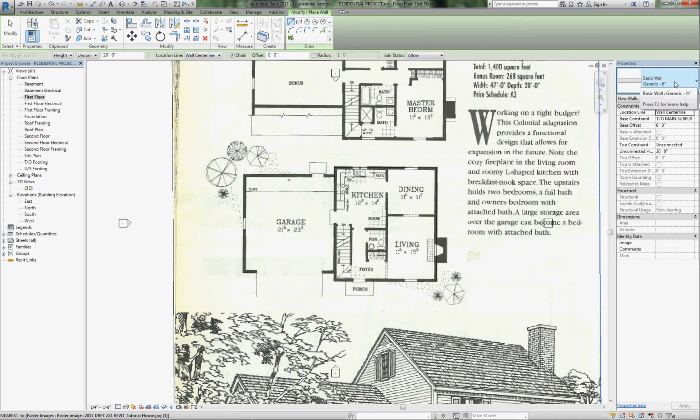Now that we've got the floor plan image inserted and the rotation correct, we're just about ready to trace over our walls. If you look closely, you can see the exterior elevation icons here, and our image is not quite centered on that. So I'm going to take my image and the few lines that I've drawn, careful not to include the exterior elevation point, and just drag it into the middle. That will save us a little bit of time later on.